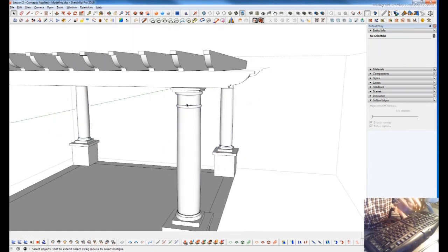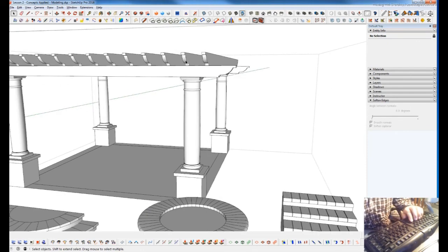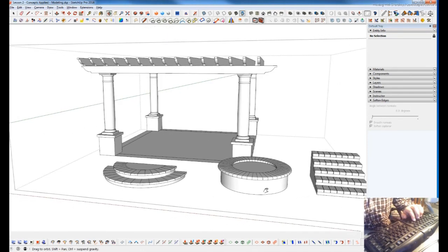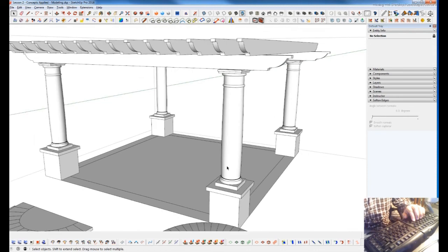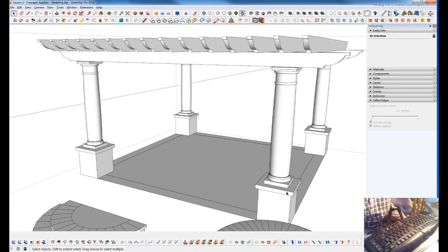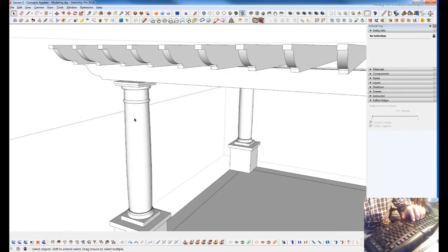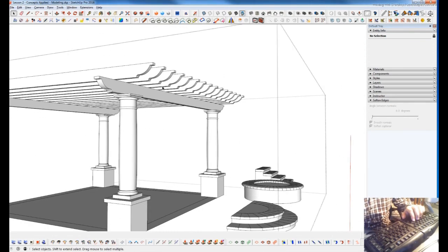And those things that I just fixed, they don't show up in SketchUp generally. You can get away if you're just presenting this in SketchUp and it looks right visually in SketchUp, that's good enough if you're not rendering. But even out of SketchUp, if you use a render engine that's in SketchUp, ShaderLite, TheaRender, V-Ray for SketchUp, any one of those shading issues, those overlapping surfaces, they'll show up later, and you don't want to have to go through and spend an hour rendering something and come back and look at the render and see that it was screwed up.